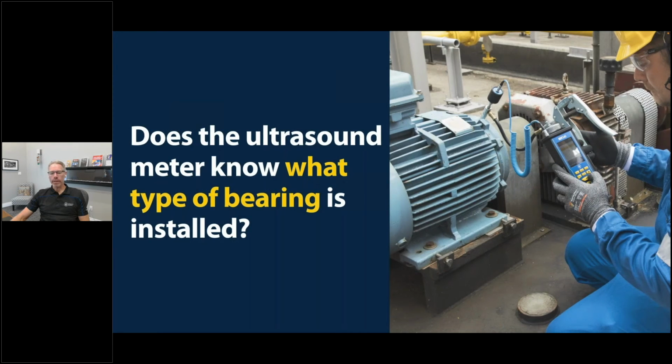The speed of the bearing is also critical. The lube expert solution wants to know on every asset, on every bearing, what the rotational speed is going to be. The reason we need to know this is because after you inject grease into the bearing, you have to wait for the churning phase to stabilize.